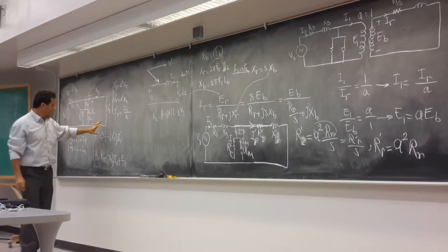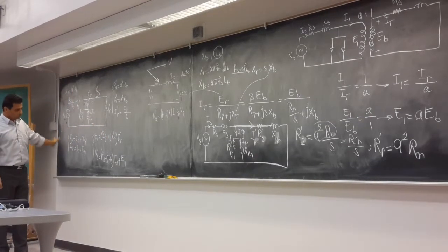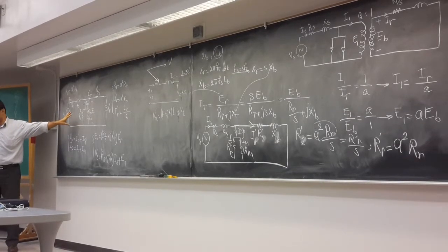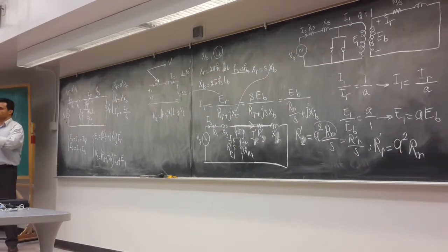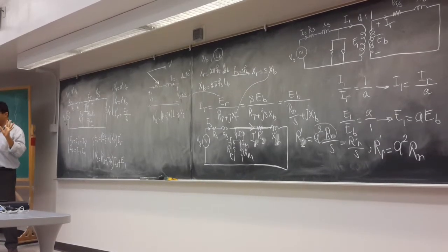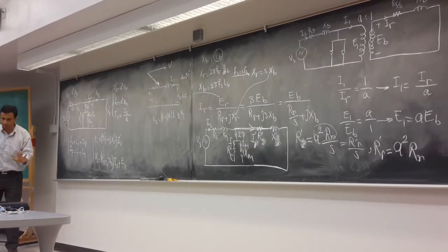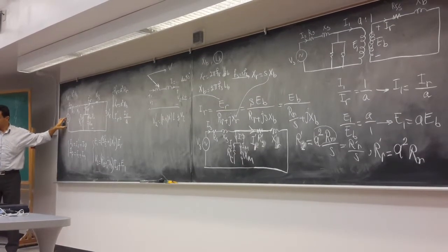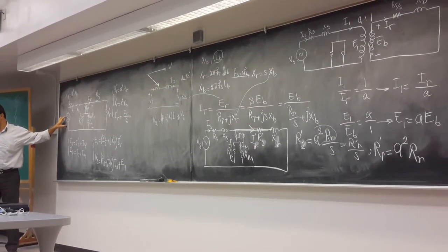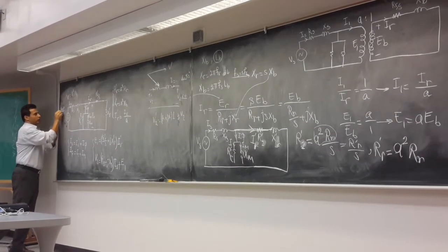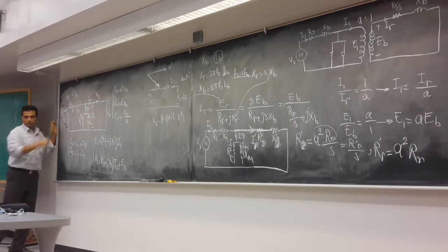So here again, in this induction machine, again it's up to you. If you want to select a crazy thing as a reference, select it. There is no problem with that. Usually the easiest way is that this one is the reference. For example, I say the machine is 208 volts, so basically it's going to be 208 over the square root of 3 with a 0 angle.